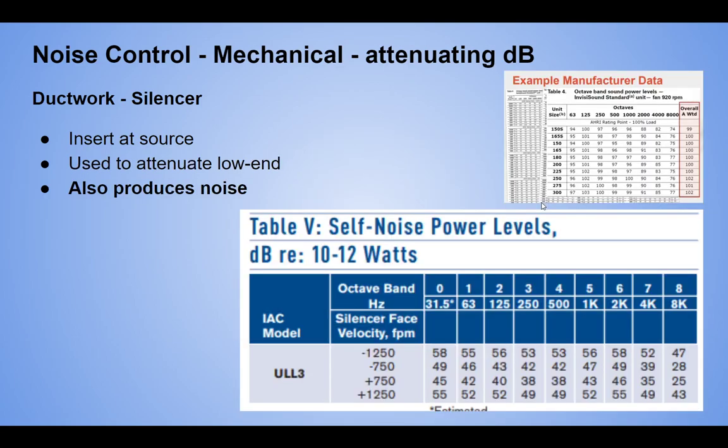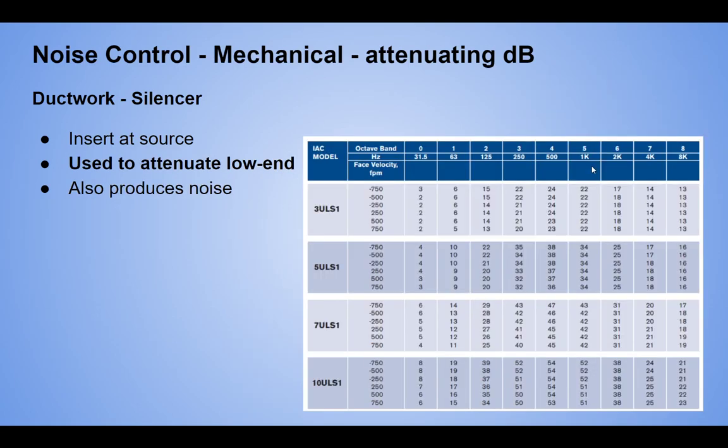But we need to be aware that it's also producing noise. And the thing to note is usually these are already higher, right? And so if we're outside of 10 dB, we don't add the sources together. So what we're looking at is we come back here, and at 200, or let's use 250 hertz, that's the one we needed. We've got an insertion loss of 22 dB.